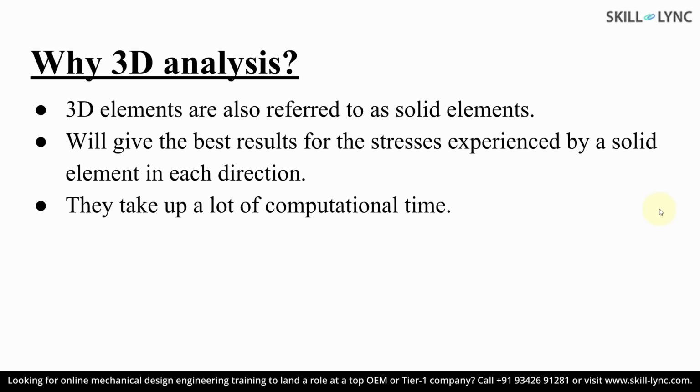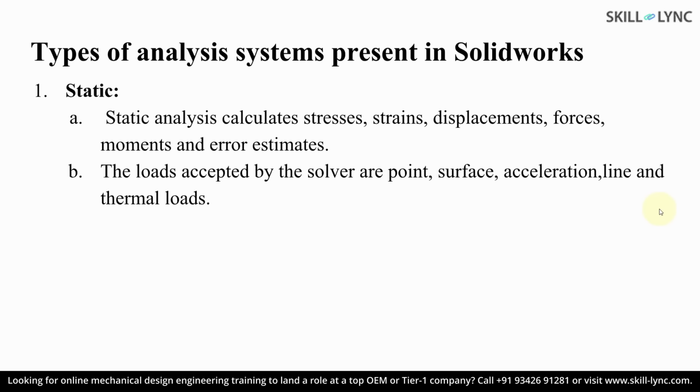Now finally the 3D. Once you have obtained all the required results from 1D and 2D, but still you want to understand the stress produced on the whole model, you tend to go for a 3D analysis, which is computationally heavier. We have solids to represent the models here. Finally, after the simulation is done, we look at the various stress and strain plots to infer our findings from the simulation. We'll be looking at how to perform a 1D, 2D and 3D simulation on a beam problem in the next video. So now let's move on.